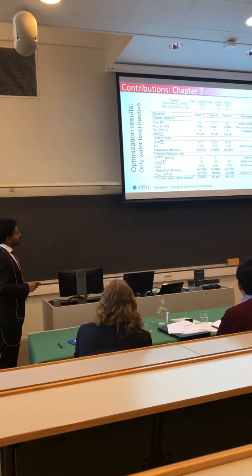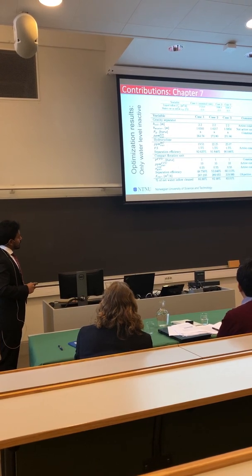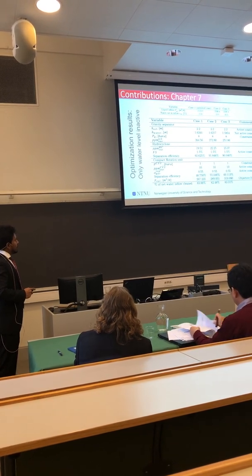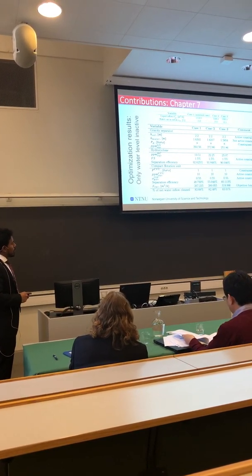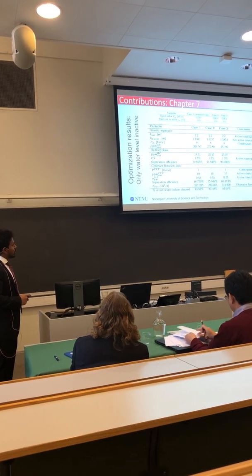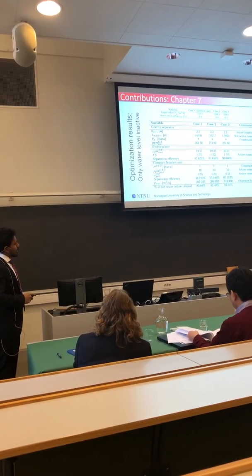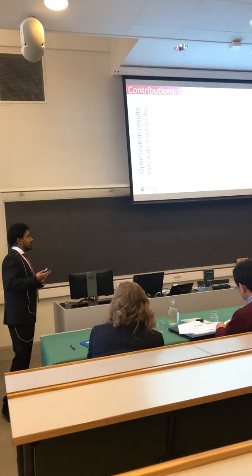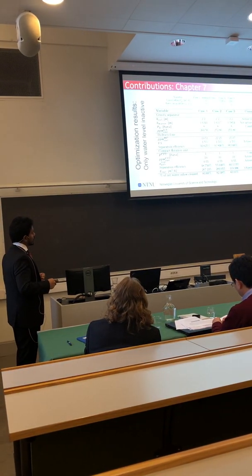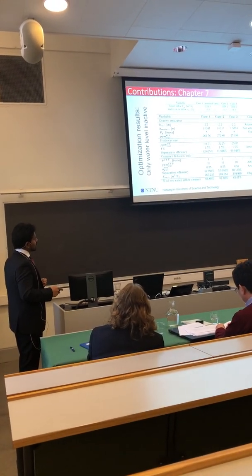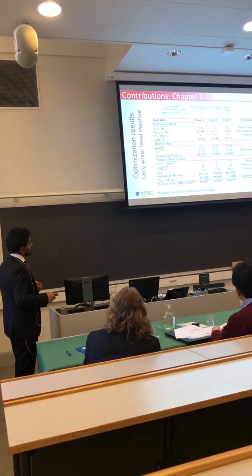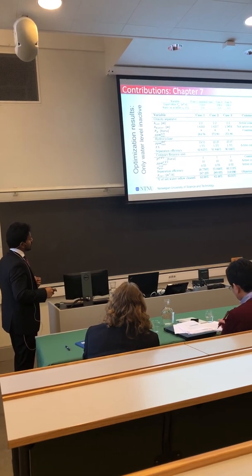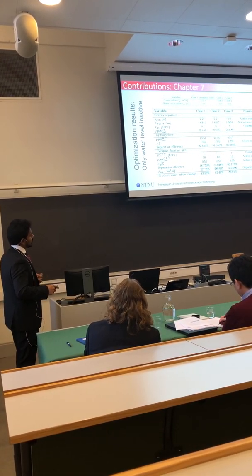I also mentioned the separation efficiency in the range of 90% for the hydrocyclone part, which is computed as the ppm out divided by ppm in. Here we have the CFU pressure, the ppm out of the CFU, and the gas hold-up at the top, which is again at 55%, which is the highest limit, because keeping the gas fraction high is optimal, which we also saw in the previous chapter. Here we also demonstrate the separation efficiency, and I also quantify how much water we are able to throw out. Here it is 83% with a higher water in higher flow.